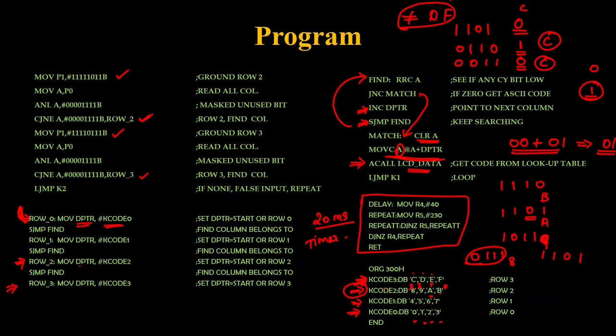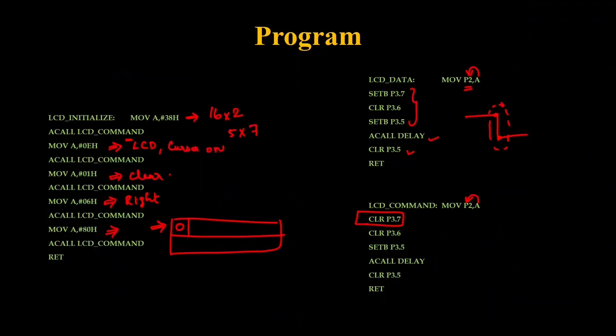So move that value of DPTR; the corresponding value of DPTR is loaded inside your accumulator. After getting that value inside your accumulator, I can send that value to your LCD screen, right? I think this makes clear sense in terms of understanding the 8051 interface with your keypad and your LCD screen. Now we can directly enter the real-time interfacing.